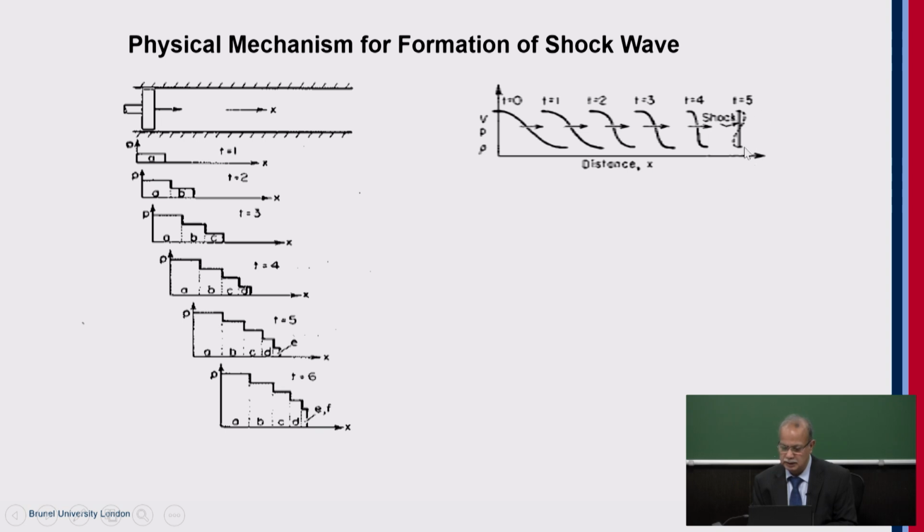For example, at a particular time instance there would be two or three pressures, which is not possible. When it comes to that situation, the flow spontaneously jumps, and that is what we call the formation of the shock waves. In common terms, the pressure waves coalesce together to form a high pressure wave. That is the shock wave.